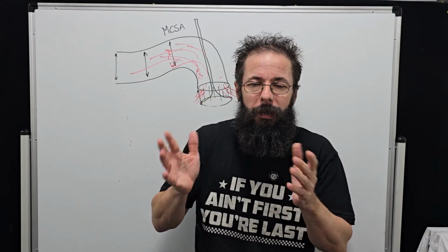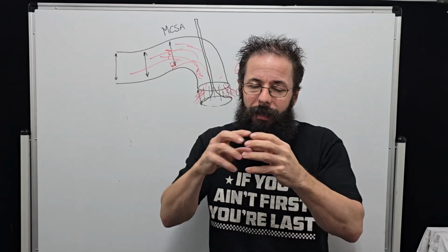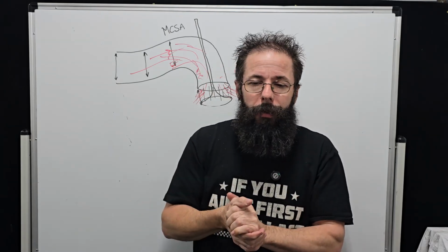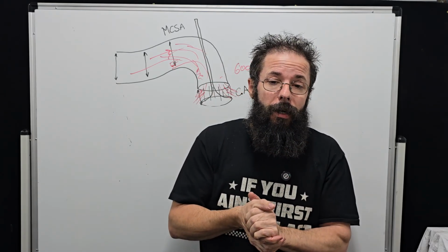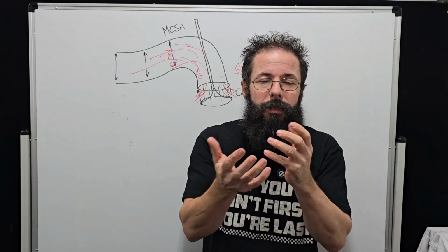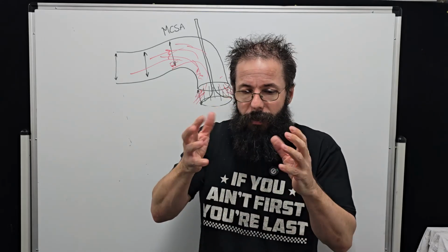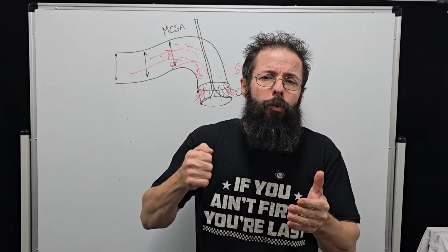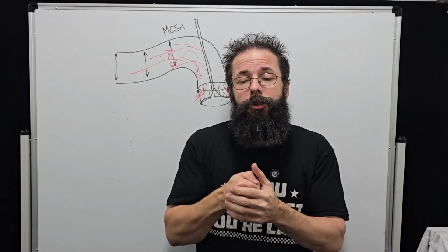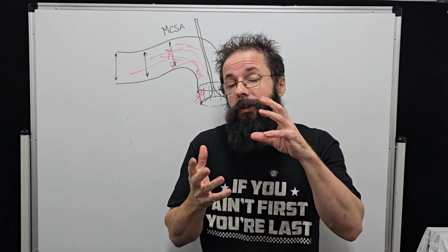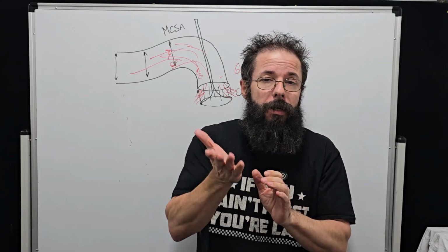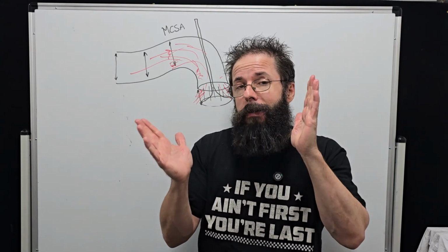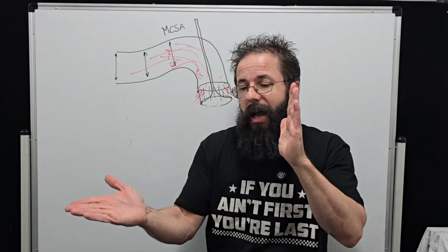We actually port mold pretty much every head we're developing. And it gives you a really good indication when you see a port mold rather than looking into a port. It really tells you a whole other story on the port, and it's easy to measure cross-sectional area as well and just see how it's going to flow visually. So be really, really careful going off what OEM have, and most of the early stuff was too big, so in some cases you actually want to shrink it down to lift that velocity up. But obviously the balance from entry to valve seat is key.